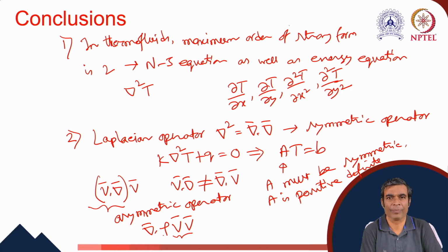The divergence of a second order tensor becomes a first order tensor or a vector. The Navier-Stokes equations are a conservation statement of linear momentum, so ultimately they are vector equations. So this divergence of a second order tensor is a vector, and we have consistency. And then V bar V bar, this outer product, gives us non-linearity.